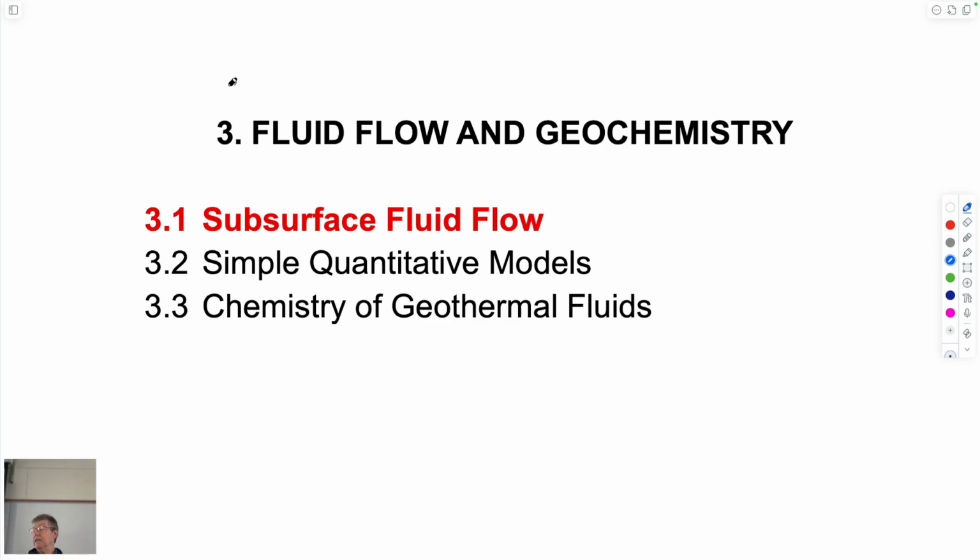So the next thing we'll talk about is what we started off with today, and that is the idea that in pushing a fluid through a system and allowing heat to conduct to that system, we're able to pick up thermal energy. It's manifest as a change in temperature in the heat transfer fluid. And so if we want to understand exactly how that can happen, then we should look first at being able to define exactly how fluid will go through the system.